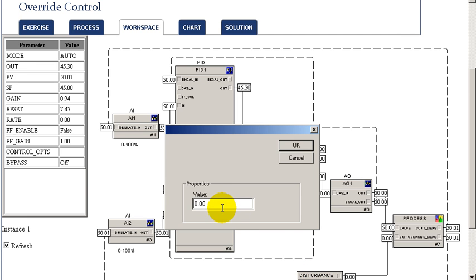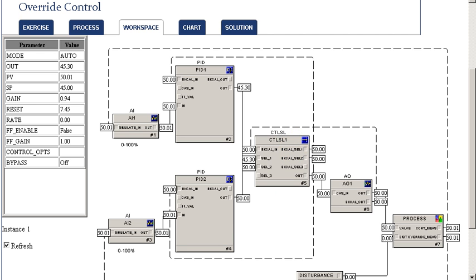The relationship between a control and a constraint parameter is very much impacted by other parameters of the process. To illustrate this, we're going to change the disturbance by step. And as we notice, by changing that disturbance input, the constraint parameter now is impacted. It's actually increasing. And as a result, the output of that changes because we're quite a bit above now our constraint limit. As a result, now the main controller here can achieve set point, its output is selected, and we're able to achieve set point because our constraint parameter is quite a bit above the low constraint limit determined by the constraint controller set point.